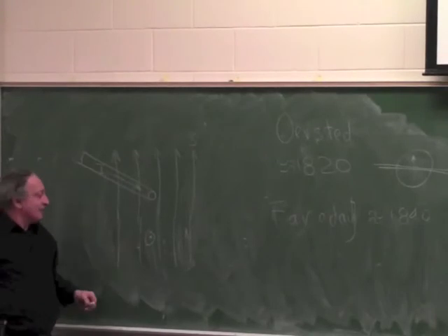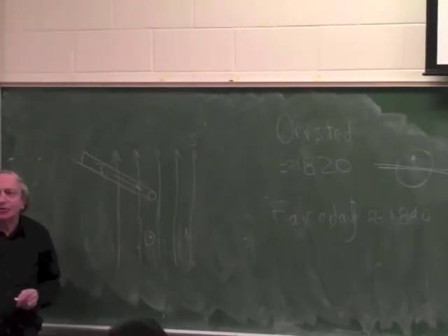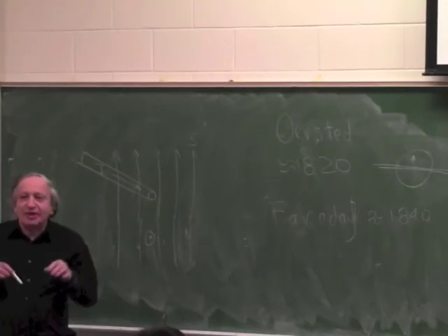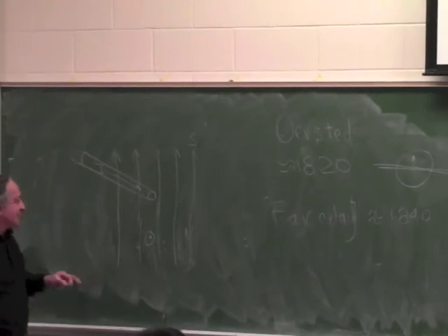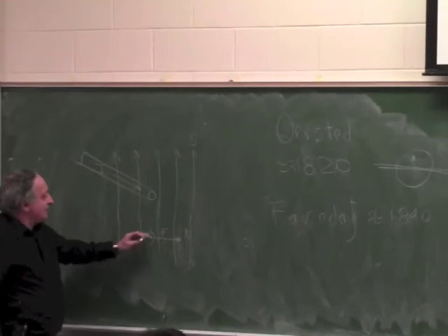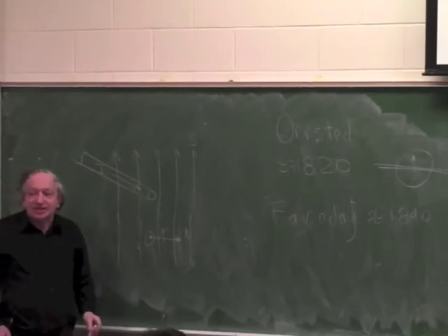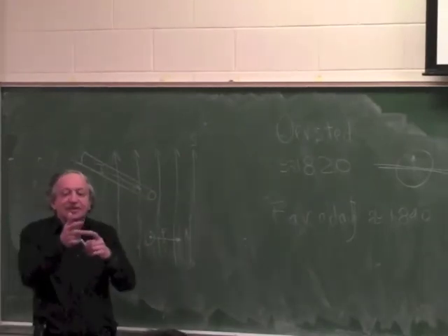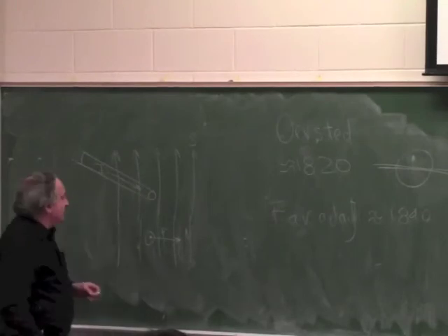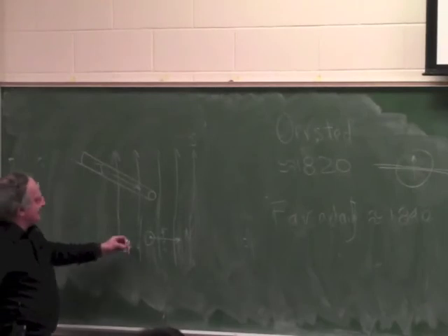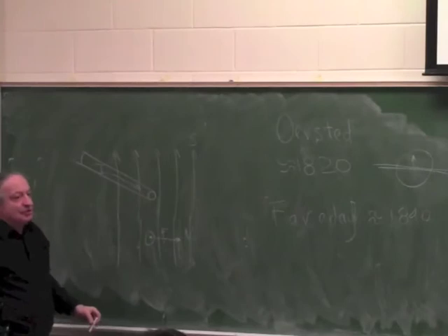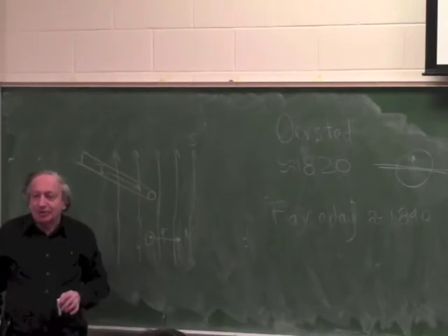Now a force will be created, and there is a rule called the right-hand rule which tells us the direction, but you're not required to remember the directions, just to remember there will be a force which is perpendicular to the current and to the field. So the current, the field, and the force are three perpendicular vectors, which also means that if this conductor is not perpendicular to the field, you'll only get the projection, which is perpendicular, creating force.